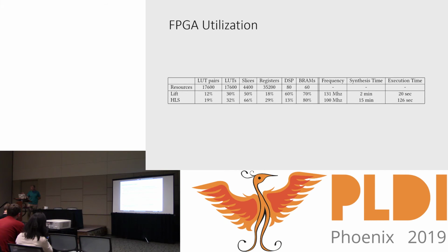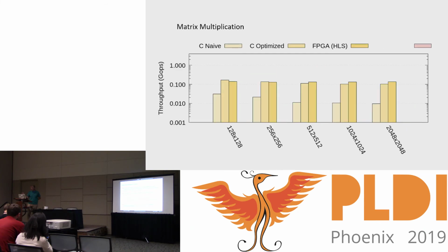But at different points, we run into different resource limits. For example, what I show here, the kernel size of the FPGA is always the small size of the matrix multiplications, and the others are using tiled versions, where the tiling would be performed on the host, and only the kernel of this size would be run on the FPGA. And that's an example where we run into the memory limit of the FPGA, the capacity of the block RAM.